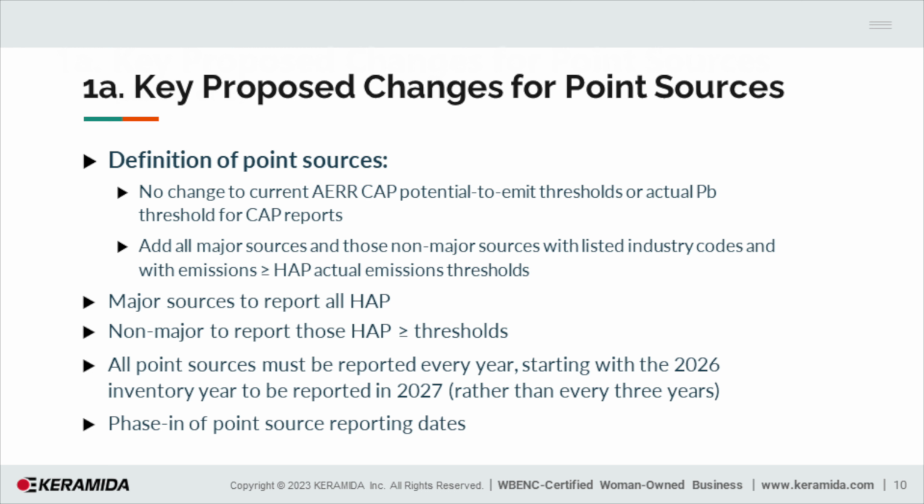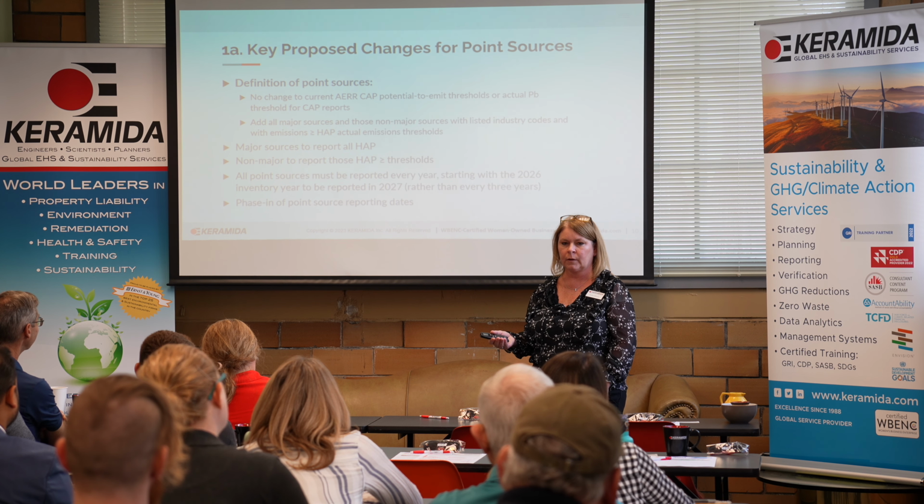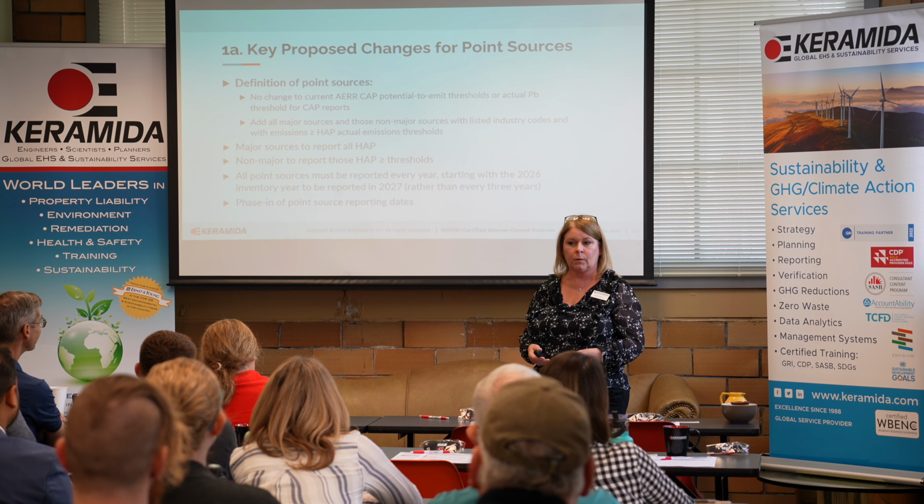Also right now, specifically in Indiana, the way that the state rules are written for requiring reporting is that some very large sources have to report their emissions annually. Other somewhat large sources only have to report every 3 years, depending on the county that you're located in. And then a lot of sources don't have to report at all. So if you're not a Title V permit facility, you don't have to submit emissions to the state. For all the companies that have either FESOPs or minor source operating permits or even lower level permits, you may get pulled into reporting even though your permit doesn't specifically tell you you have to do it.